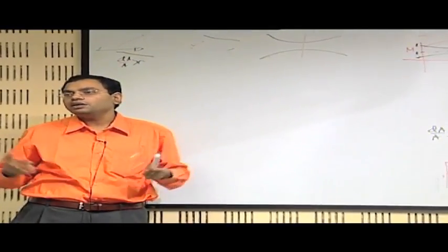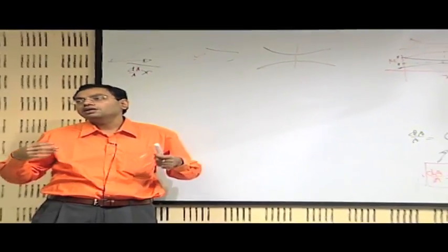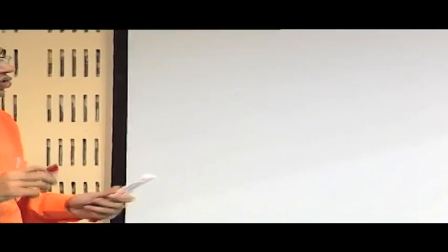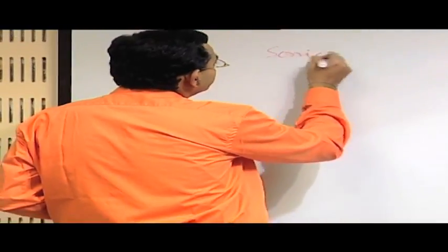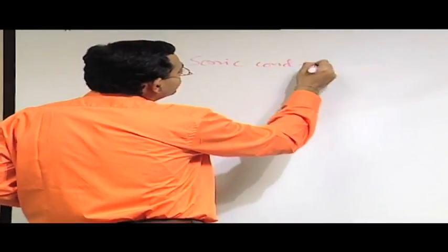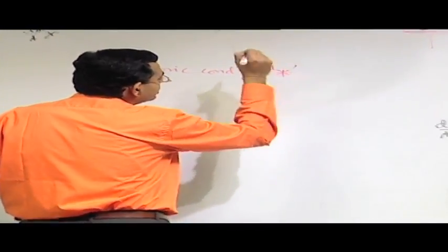Although at dA by A equal to 0 sonic condition need not necessarily be achieved, but if it is achieved at all, it is achieved there. Now when the sonic condition is achieved, these sonic states are usually given by a quantity star in the description of the flow. So this is just a symbolic way of representing.